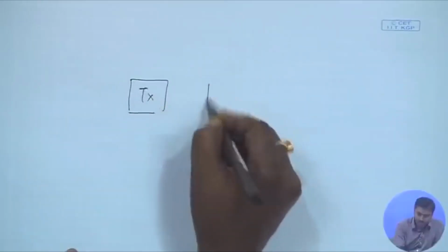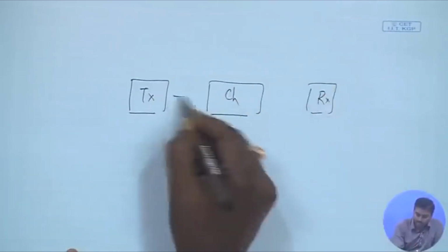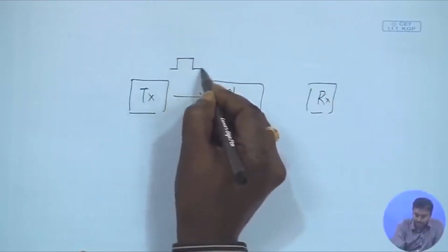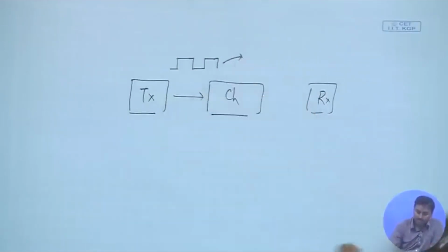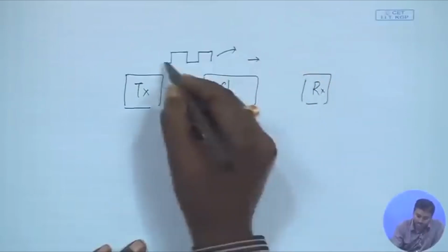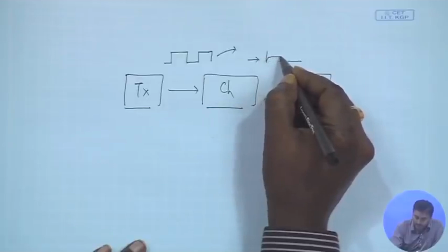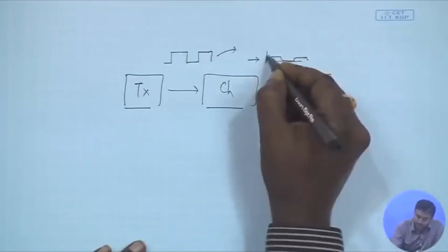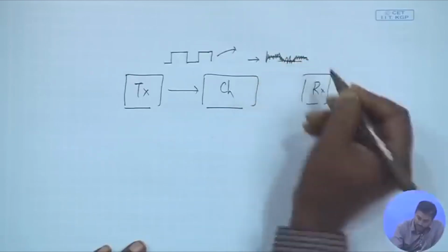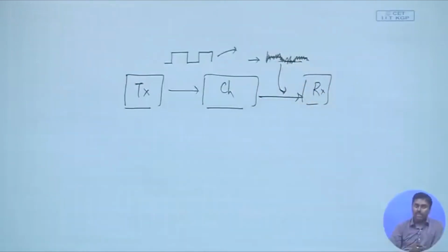These three things should be very clear whenever you are transmitting, because eventually, as we have discussed, any signal you transmit, so we had this transmitter, we had this channel, and we had this receiver. So this is actually the transmitted signal. The transmitted signal may be very nice, but due to the channel, and I am just taking out the interference as well as nonlinearity of the channel, even if we take out that, what will happen after passing it through the channel, this particular signal will become like this. It will be something like this, and on top of that there will be noise added randomly. So this is actually going to be your received signal, and that is why we said the transmitted signal and received signal might not look alike, they might be completely different.